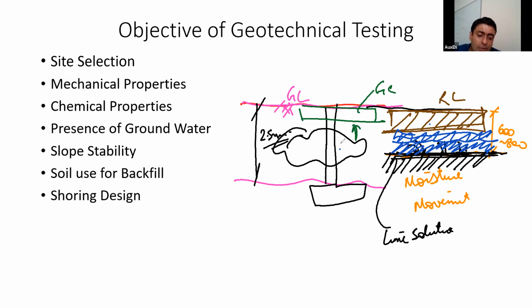Prasad sir is asking plum concrete is good option or soil replacement. See, plum concrete again, how much plum concrete you will do, isn't it? You cannot do a 600, 800 mm plum concrete. That is too costly. So soil removal, soil stabilization to a certain extent, and replacing it with some muram is cheaper than filling it with plum concrete.